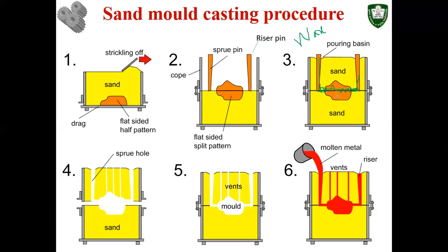You place them in position, and then you fill up the whole flask. You pack it properly, and then you make it upside down. That means if this is the top side, you make it upside down, and then apply heating. Okay, apply heating from both sides, or any other side, from all sides you apply heating.